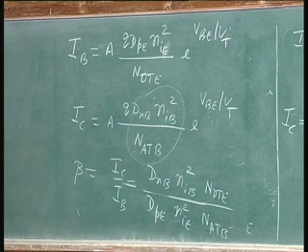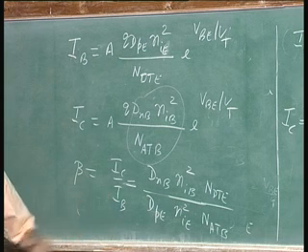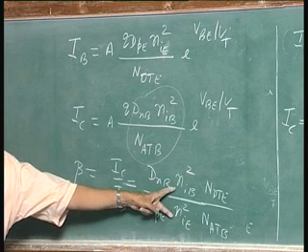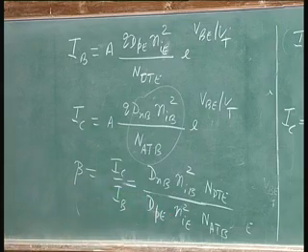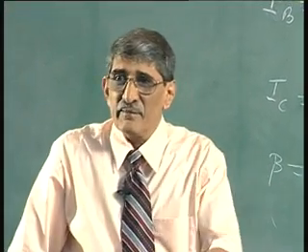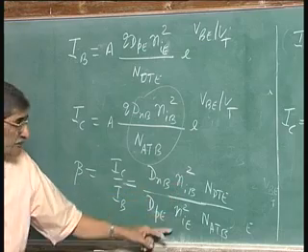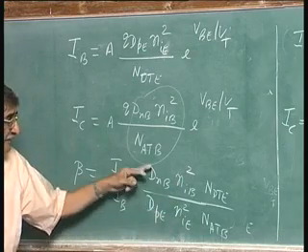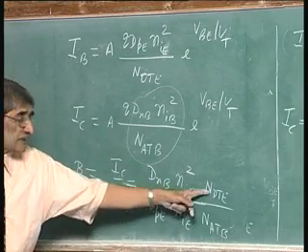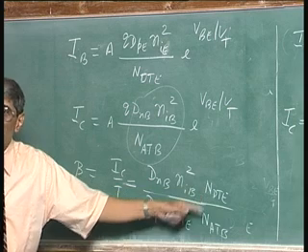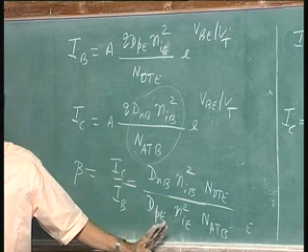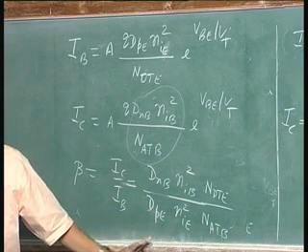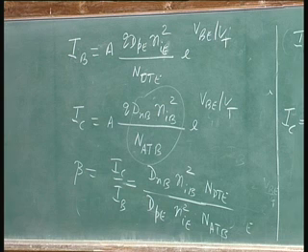It is the same equation that you have been writing maybe in your first course, but the difference is I have added these two things. If the band gap is the same, Ni will be the same in the emitter and the base, that will go off, and beta will be decided by DNB by DPE, and the total integrated doping in the emitter divided by total integrated doping in the base.